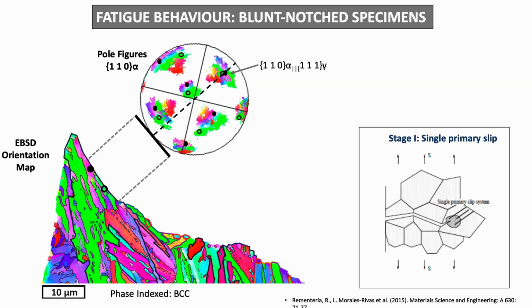So it indicates that in that case, there is less restriction for slip, or dislocation slip, to be transmitted across the interfaces between bainitic ferrite and austenite that we cannot see with this EBSD map.